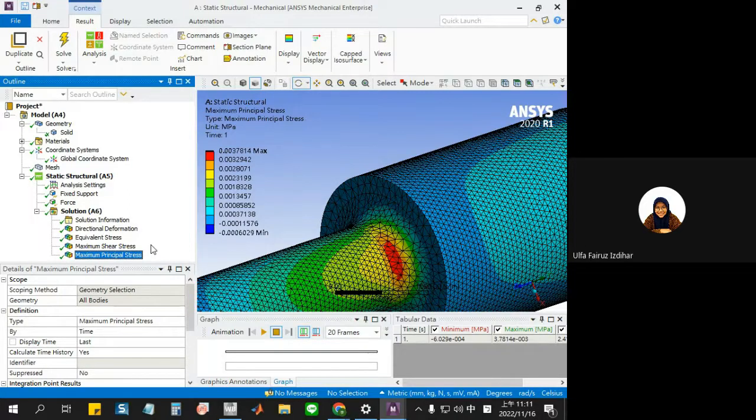If you use normal stress, then your normal stress needs to be smaller than your yield strength over safety factor. So at the end, these two are the same model.